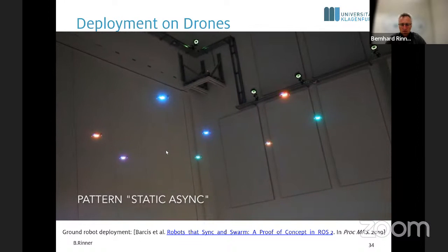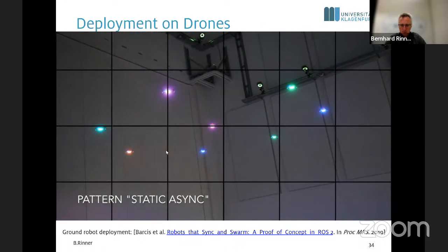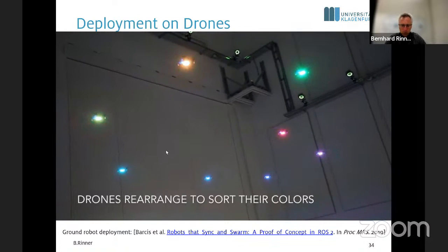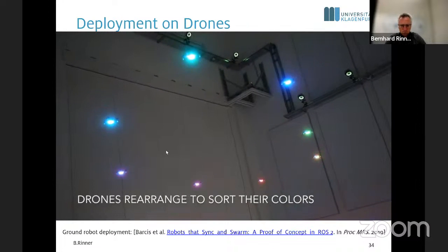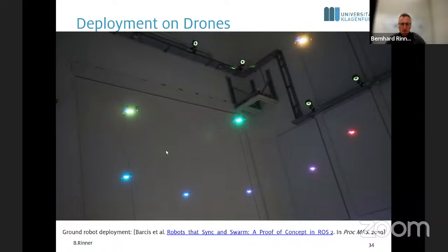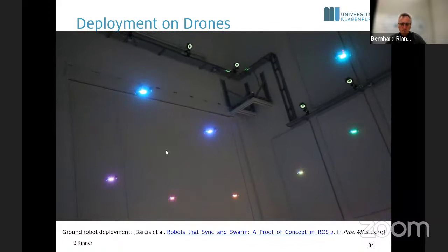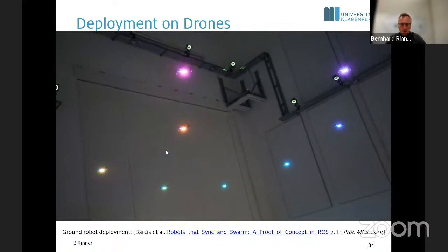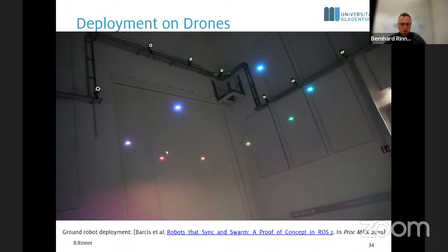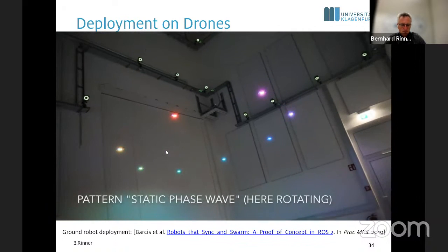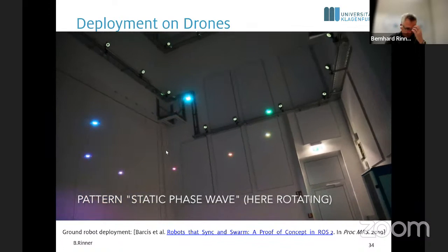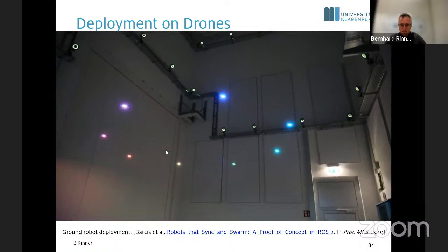Then we change the parameter. We see this async model. By applying different parameters, we see this kind of ring approach where the nodes themselves arrange. It's important to mention that the movement is simply based on these coupled swarmulator models. Right? So what you see here is that these drones arrange into a specific formation. It's a ring, and their neighboring phases are adjacent to each other.